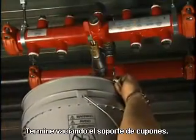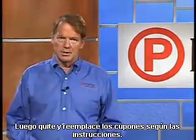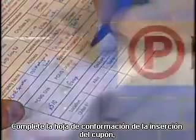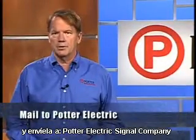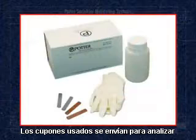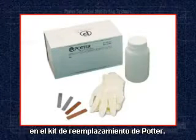Finish draining the coupon rack. The coupons are then removed and replaced as instructed. Completely fill out the coupon insertion confirmation sheet and mail to Potter Electric Signal Company in the envelope provided. The old coupons are then sent in for analysis by using the shipping label included in the Potter replacement kit.